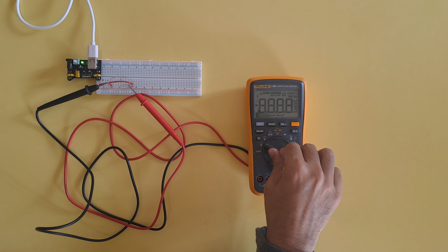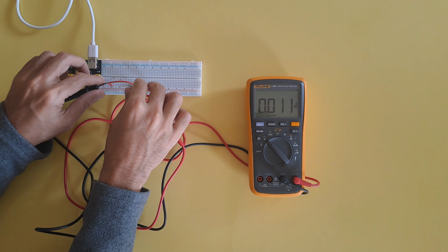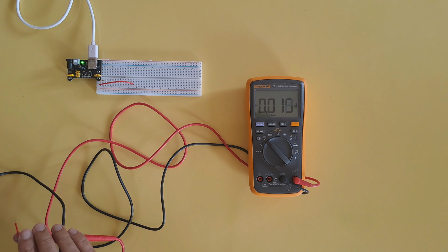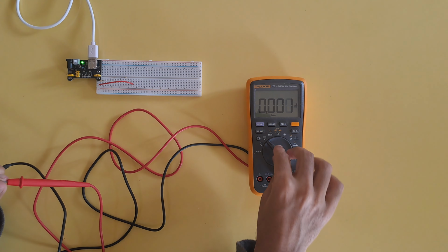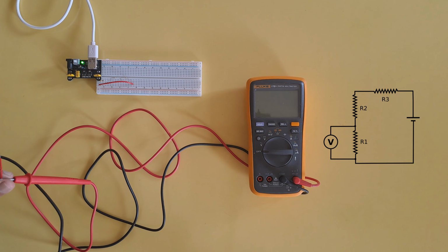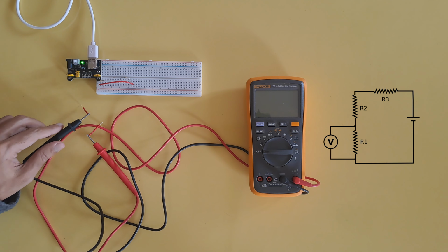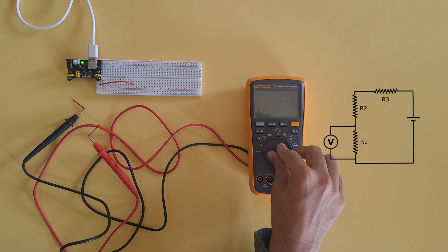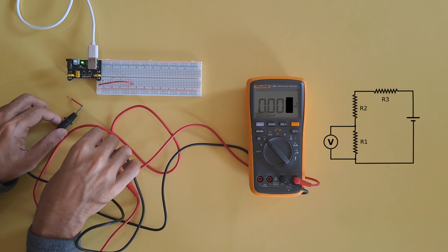For the final experiment, we are going to use a multimeter. A multimeter is a device used to measure everything electronic, like voltage, current, resistance and whatnot. For now, we will use it to measure voltage across a resistor in a simple circuit. I have connected 3 resistors in series with the power source. We will check the voltage drops only across the first 2 resistors individually and then combined.